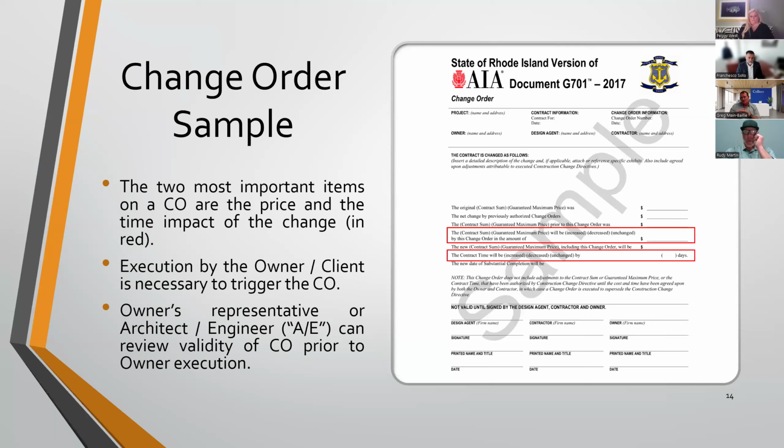So from that aspect, you really need to manage your bidding process and identify which line items are going to be unit price based. And in every instance you can, lump sum price a line item, take that opportunity to do so. That way, you're formalizing your budget, formalizing your number, understanding where those change order lines or exposure is going to be.